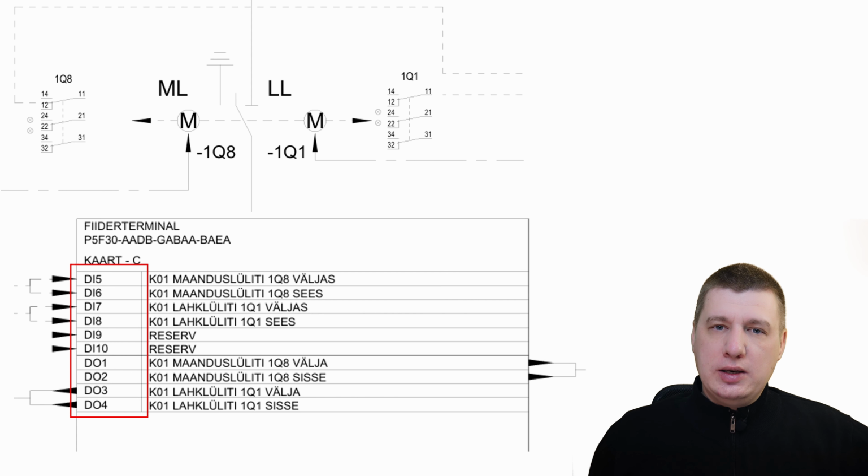Digital outputs are the relay's way of taking actions. They are mechanical contacts that close or open to trip a breaker, sound an alarm, or send a signal to a PLC. The P5 uses different types of contacts: normally open, NO, for most control tasks, and changeover, CO, contacts for complex signals. A critical feature in the P5 model is the high speed, high breaking capacity output.